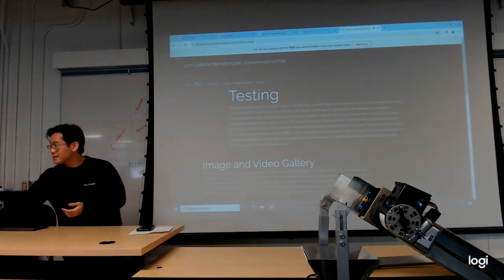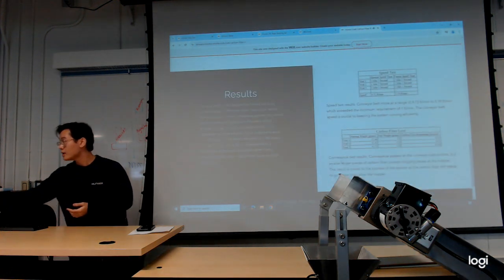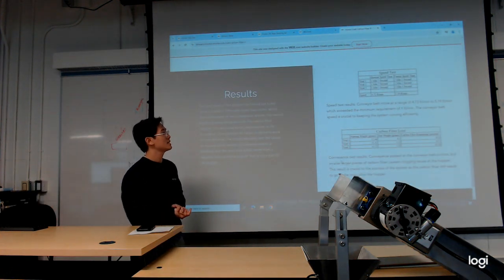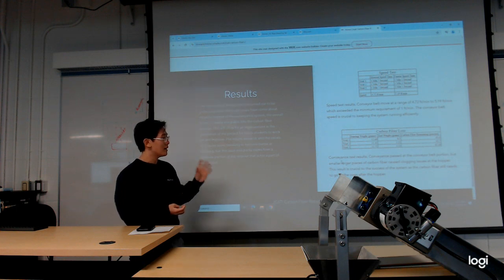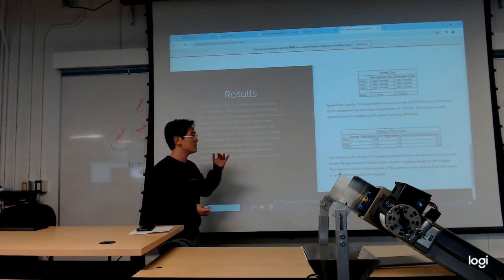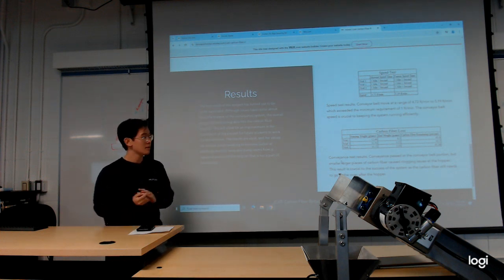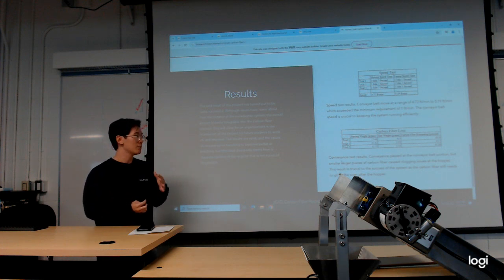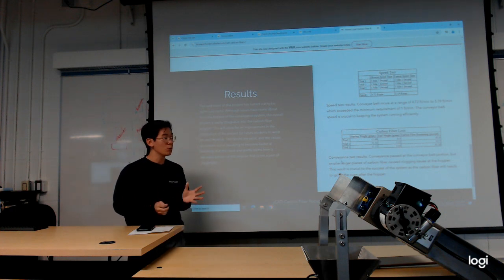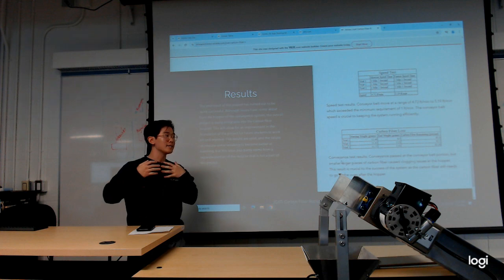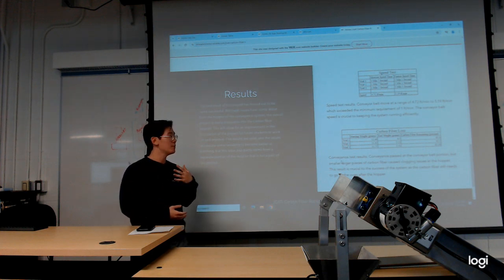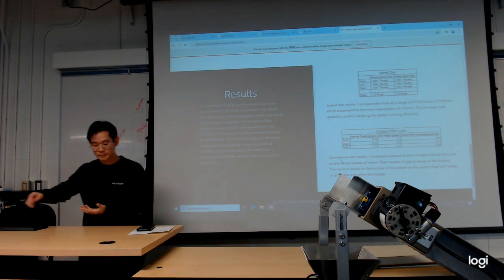And as for my results for these tests, the speed test was an astounding success. I was able to reach a minimum speed of 4.72 feet per minute and a max of 5.19 feet per minute. But I unfortunately failed the conveyance test as it was between 45 to 65%, where I kind of wanted at least 90%. But this was due to some of the larger pieces getting caught in the hopper, and a fix for this could be adjusting the rollers a little bit in the hopper, or maybe as a future iteration of the shredder, being able to shred the carbon fiber a little more finely.